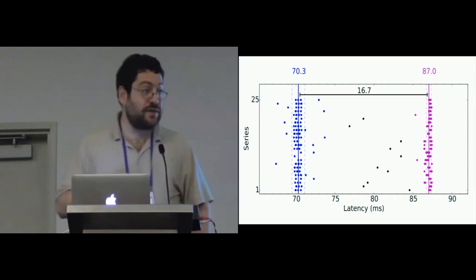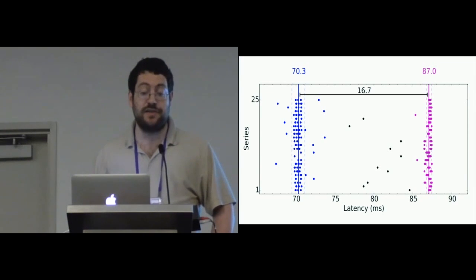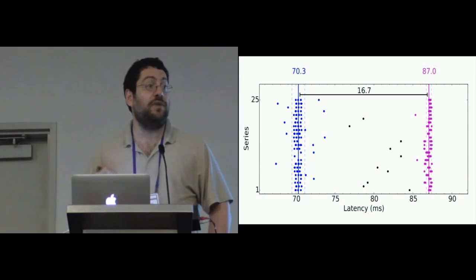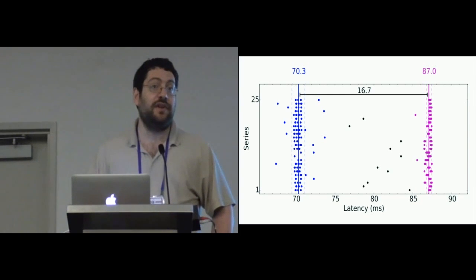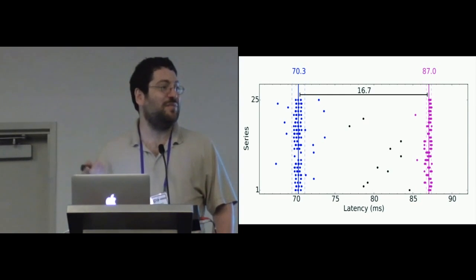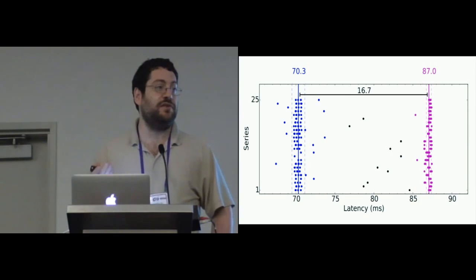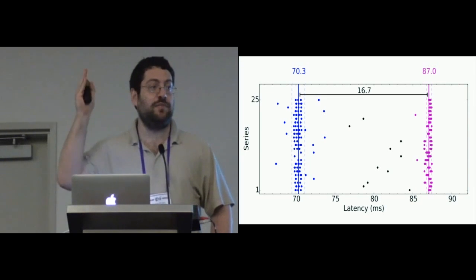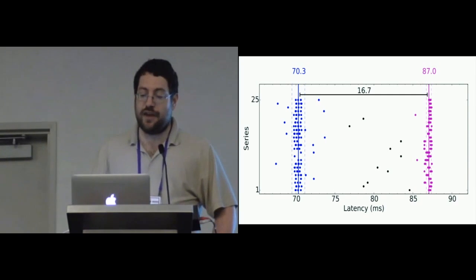What we see in terms of the distribution is this spacing of 16.7 milliseconds between these two big clusters of measurements. And the reason we see that is because a screen redraws itself only so often. At 60 hertz, which is the most common speed available today, that's 1/60th of a second, or 16.7 milliseconds. So even if a device is ready to present information to the user, if the screen isn't ready to redraw, it can't show up. So we tend to see these quantization effects that occur chunked at these 16.7 millisecond frame boundaries. So that's how the Latency Hammer works.